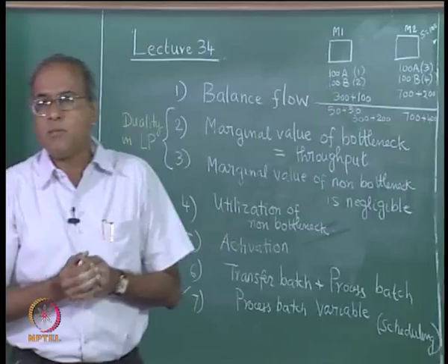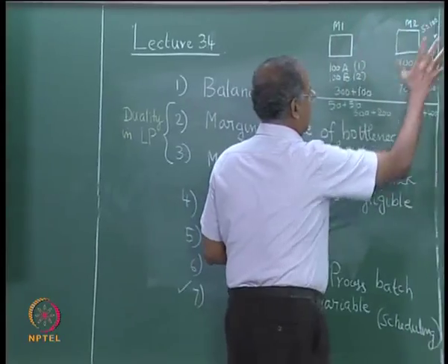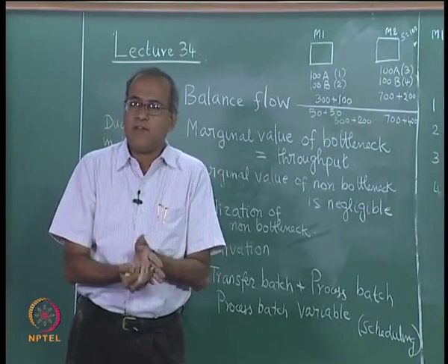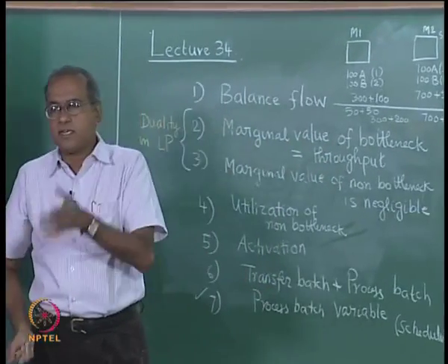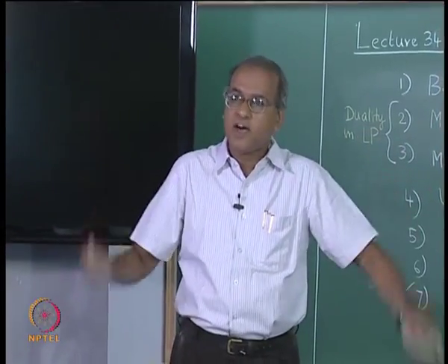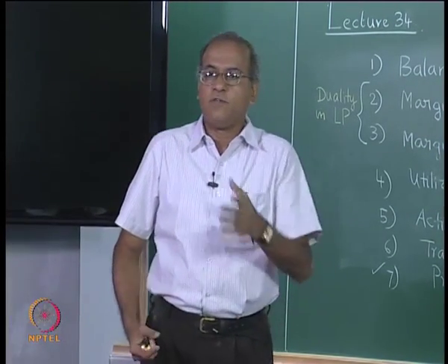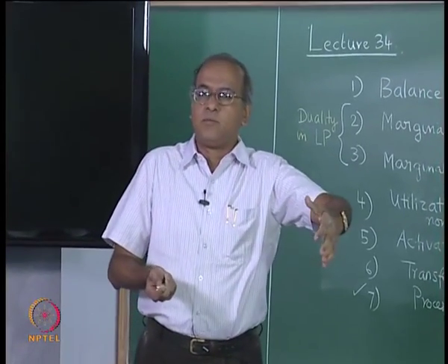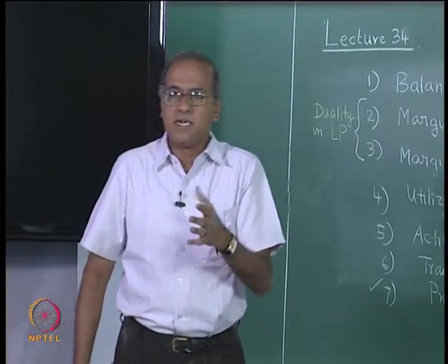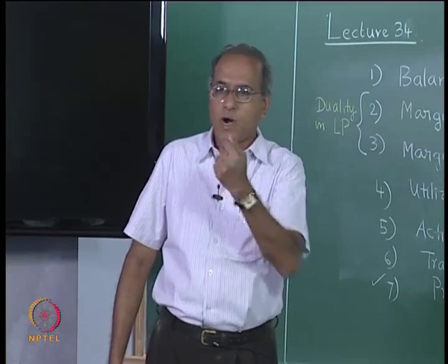One thing that we need to keep in mind is that even though in almost all the examples we write like this and we assume that there are these machines, in practice when this is not applied in the context of cellular manufacturing, we should always keep in mind that the machines are sufficiently far away and single piece transportation is not easy. So we will have large production batches, smaller transfer or transportation batch, but the transportation batch themselves would be slightly bigger than transporting one.